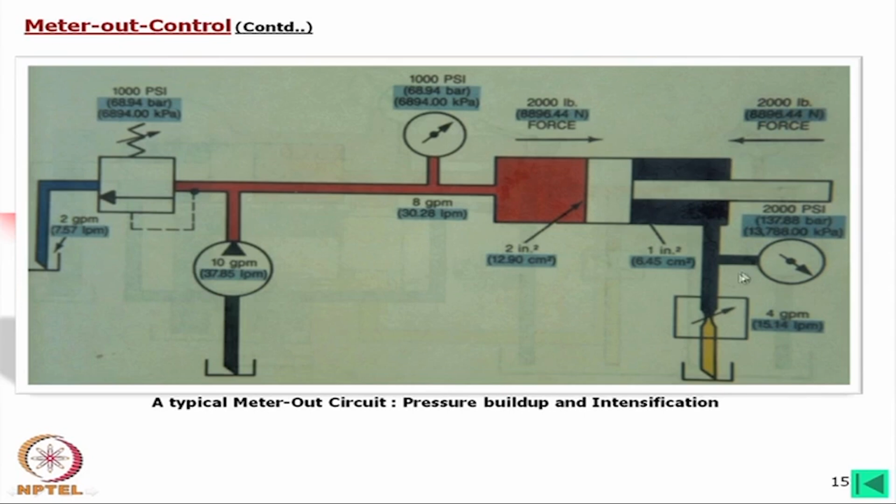So what will happen in normal course when the drill is moving? If you have operated a drill, and the material is good and the drill is properly sharpened, you may not apply much force. But whenever, for some reason, you have given more feed by hand, you will feel that it needs more force.